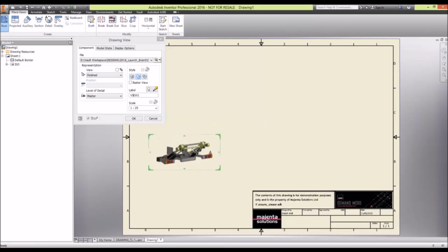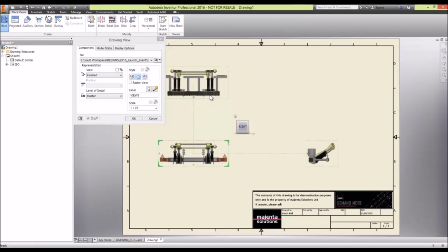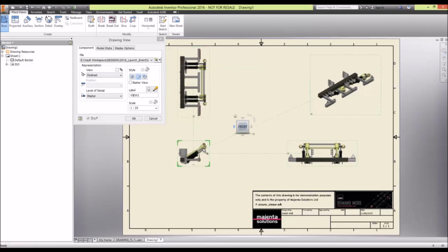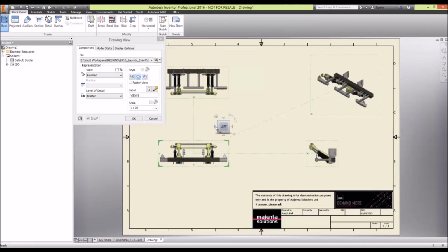So my view here is enabling me to manipulate this, move it left and right, look at a different perspective. I can also create projection views, top and side. I could produce an ISO if I wanted to. And if I now manipulate my view cube, so if I say this is actually the front view, what then happens is all the other views will move accordingly. So we can go left view if that's the right view. Left looks a little bit more left or right, maybe. We'll go left or right, we'll have a look.